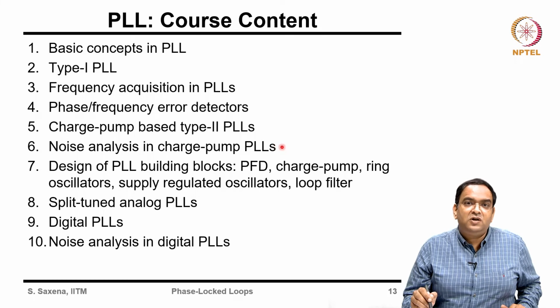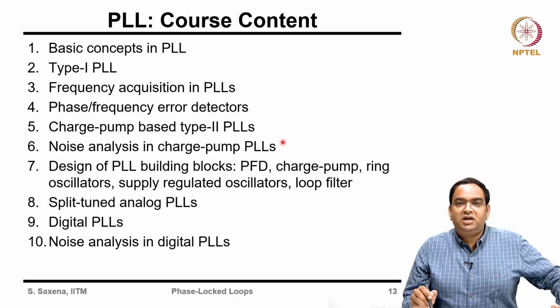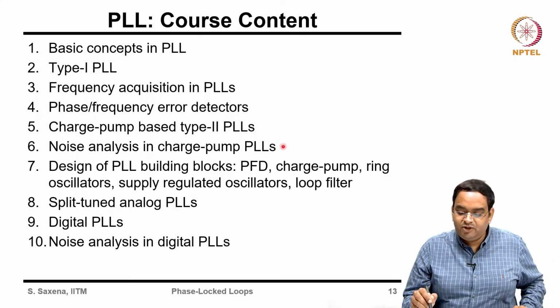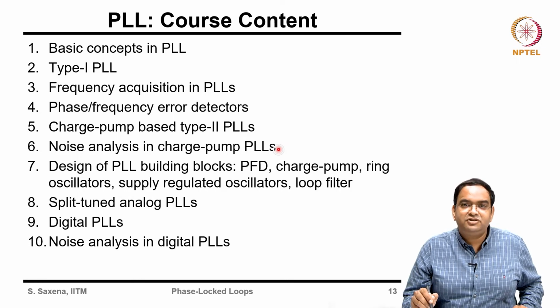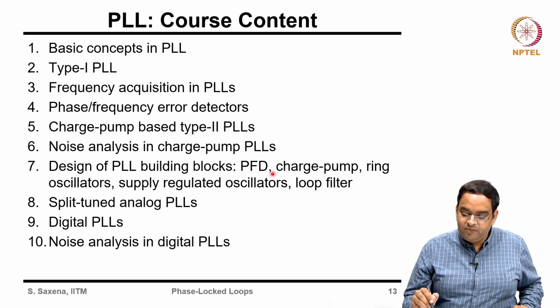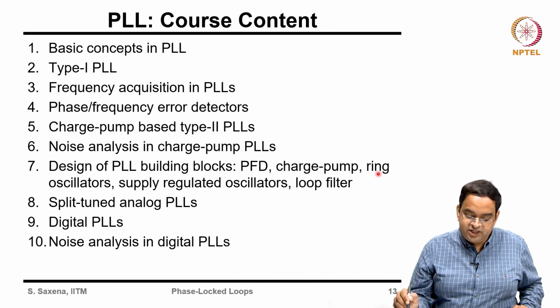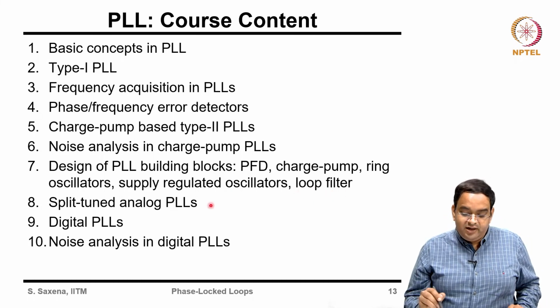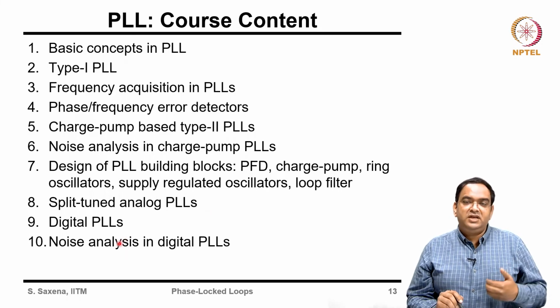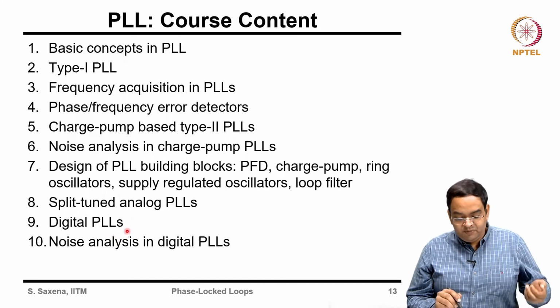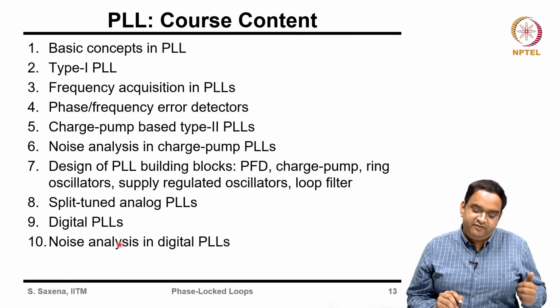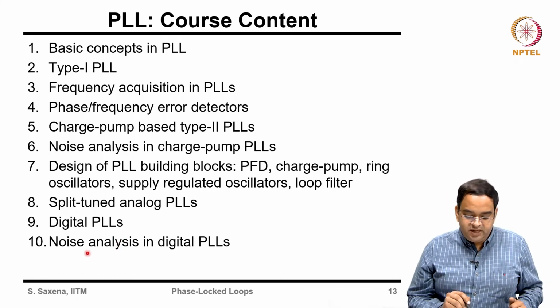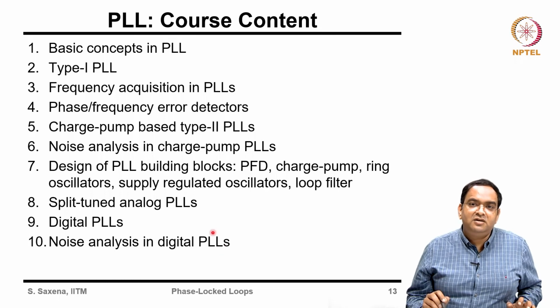Then we will see what all noise sources come. You are getting something, so there will be some problems with that. We will do the noise analysis to have an efficient design. Then we will go through all the building blocks of the PLL: PFD, charge pump, ring oscillator, supply regulated ring oscillator, loop filter. Later, we will go through the split tune PLLs. Then we will see the digital world, how to implement it digitally, what are the benefits and drawbacks of digital PLLs, and the noise analysis in digital PLLs.